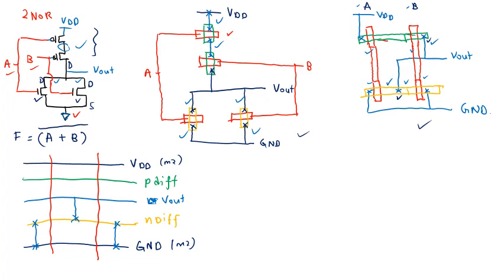Since over here we have the same type of metal, you don't need to have a cross in the middle. Right, next we have the drain side of the PMOS connected to the output. Because this is a B line here, you name it. This is A, this is B. Then the B side here should be connected to the output. So you just put a metal like this, right? And then you have the last part.